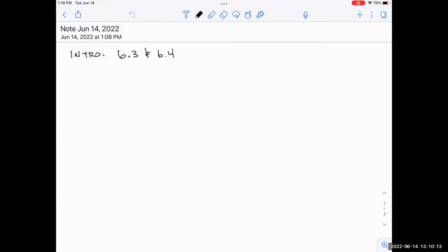lot more frequently than you would think, only because, as I said, when you have a real beam, the beam has weight, therefore you have a rectangular load automatically with nothing on it. And then the triangular load happens typically when you have something that's like a dam where it's getting deeper and deeper and deeper in the water, or a retaining wall that's going deeper and deeper in the dirt, because there's more and more force as you go down.